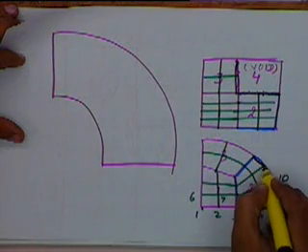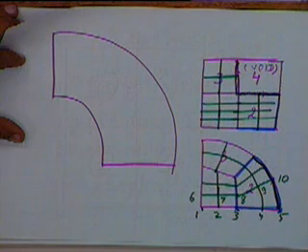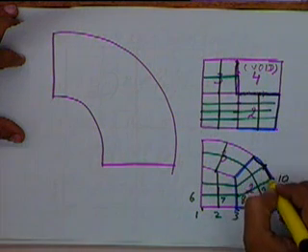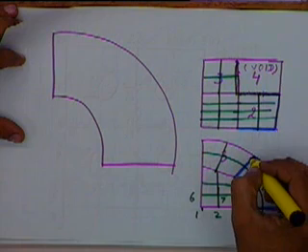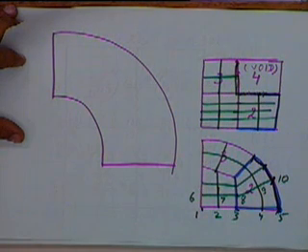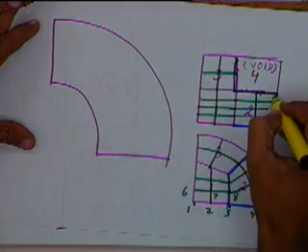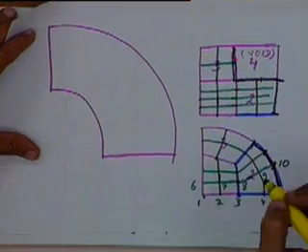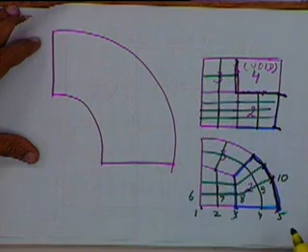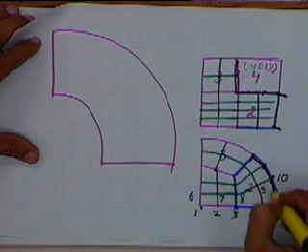Okay, if you have a 4-noded quadrilateral element, it has only straight edges. If you have an 8-noded quadrilateral, it will have a quadratic edge. Okay, so if you are taking element with straight edges, we will get straight edges on all these locations. Okay, and these points will be obtained by quadratic interpolation between these two. Okay, I know this point and I know this point, and I can do a quadratic interpolation between them to get this edge.